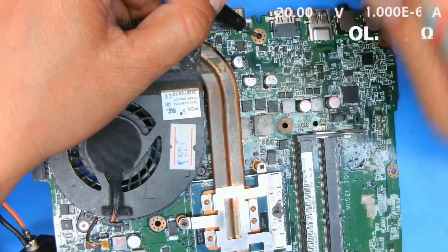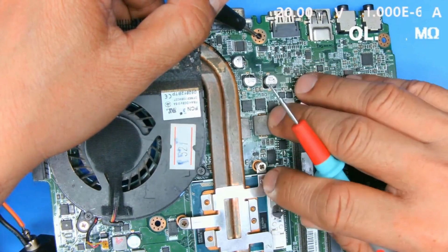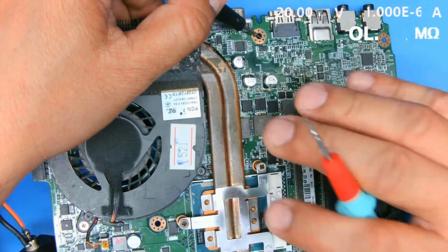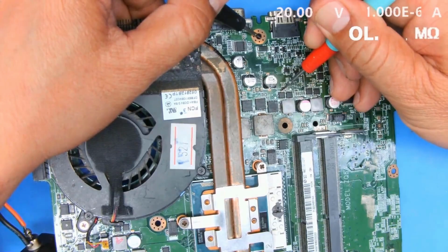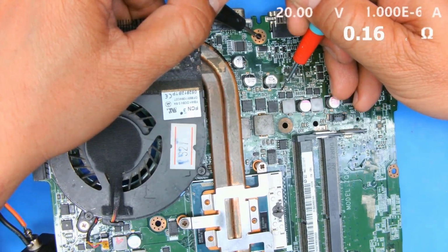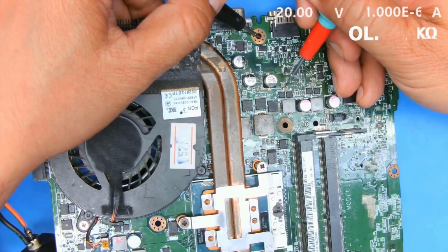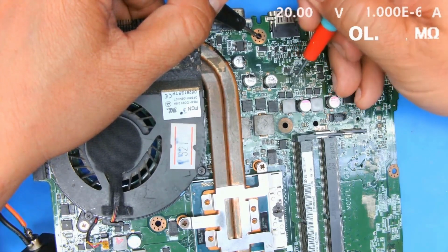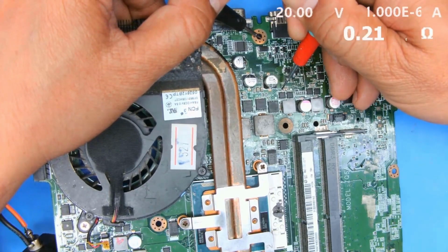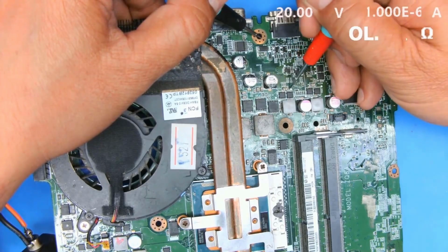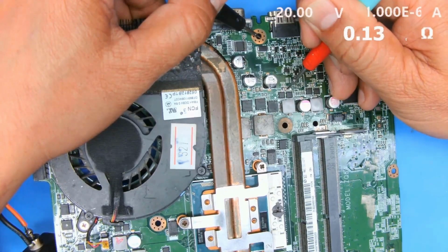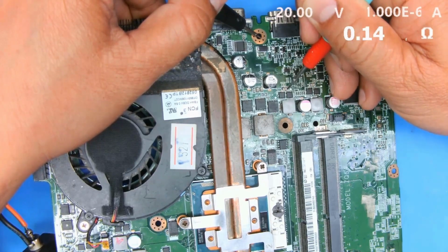The positive side. Now, if we want to supply power to find the positive or negative side, that's possible too. But in the case of a gaming notebook, if this side reads 1 ohm, right here, about 1 ohm, or 0.7 ohms, 0.6 ohms, that means it's a MOSFET high side short. If it's a capacitor short, the ohm values will be very close to each other. But if the ohm value on this side is much higher than the other side, even twice as high, you can compare it like this. For example, the ohm value is 0.140, 0.15, and if it's double, that's 0.300.